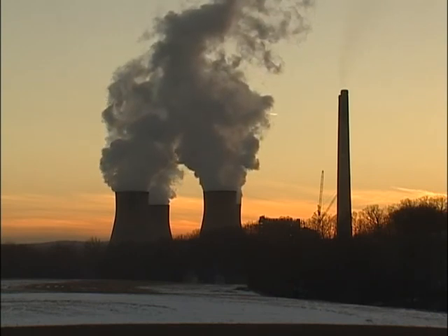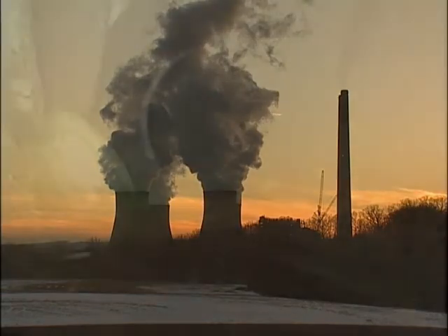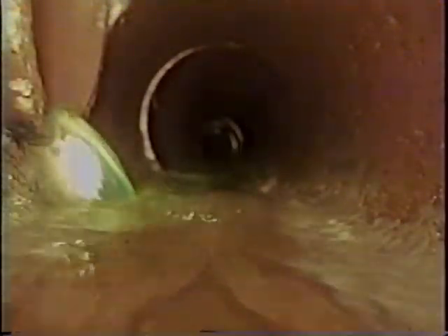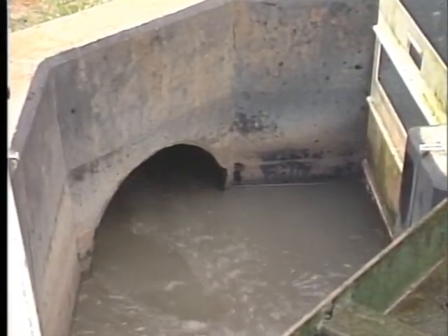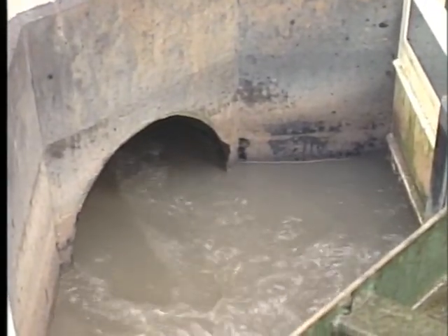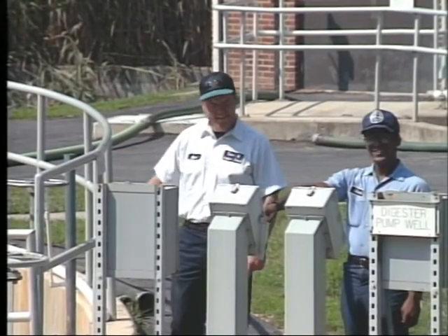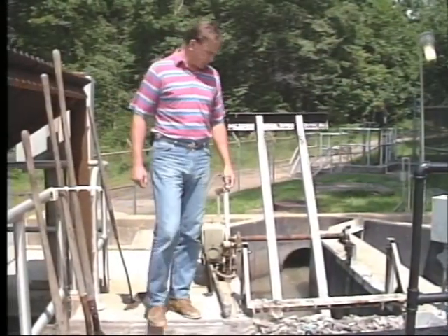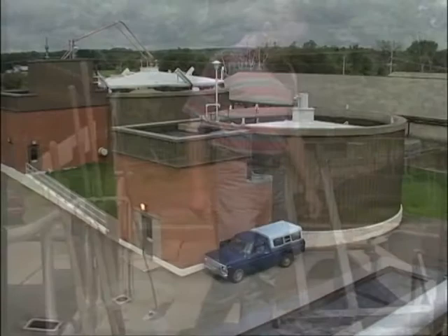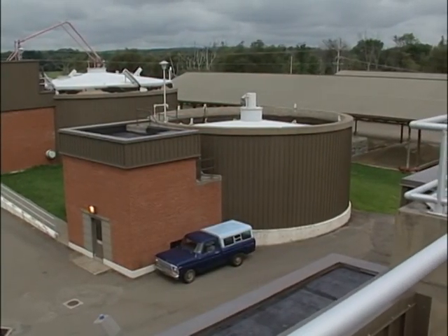After the wastewater is generated, it then goes into the collection system for conveyance to the treatment plant. In the collection system, if excess water enters the system, it can cause a washout of biological processes in the treatment plant. After the wastewater arrives at the treatment plant, the operator must monitor all treatment processes. Malfunctions in preliminary, primary, or solids handling processes can adversely impact the nitrification process.